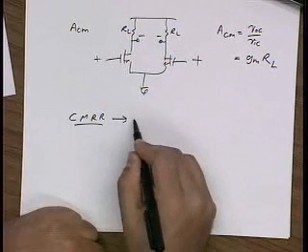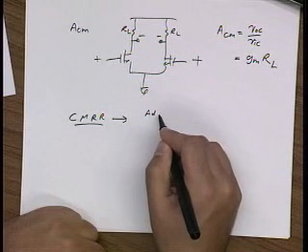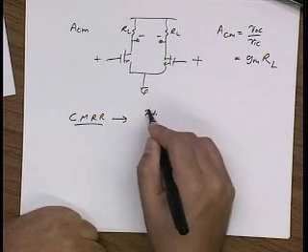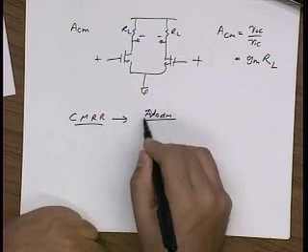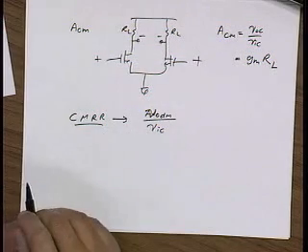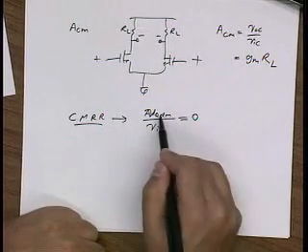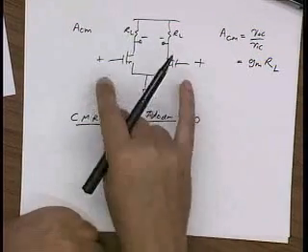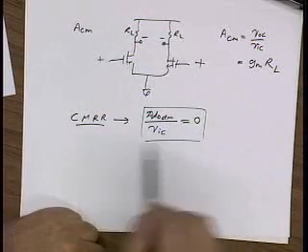This is the output differential mode. What I really care about is differential mode for an input common mode. And in fact, the differential mode at the output is 0 when I have an input common mode. And so I'm happy, right? This is kind of what I want.